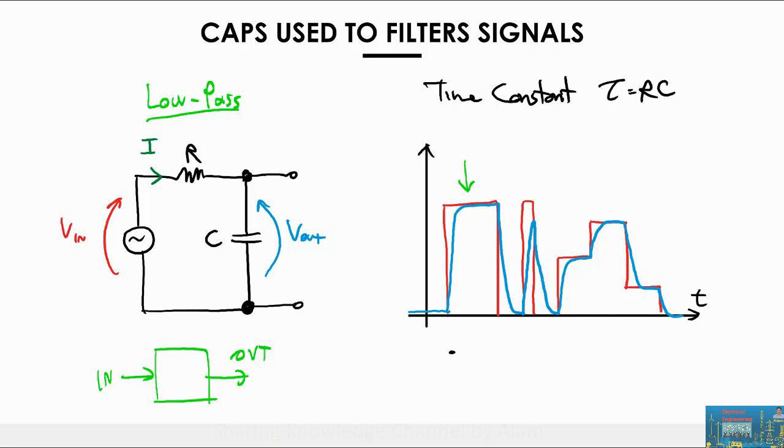but you have the whole intensity there, so the voltage actually reaches the peak. While this little pulse that is really, really fast, up and down just really fast, you still get something out, but it's attenuated. The peak is much lower now. So in the output signal, the components that want to move really fast have been removed.